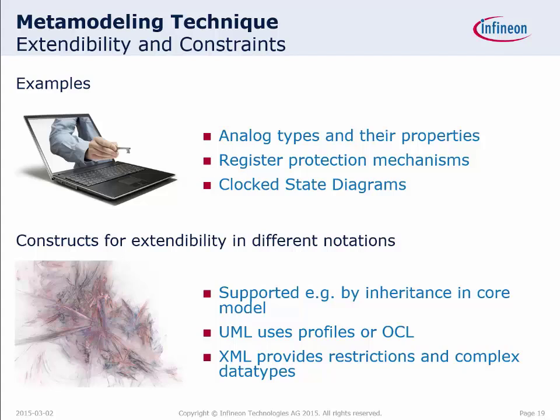If you want to do analog and digital modeling and you have a mixed-signal system, you have to deal with analog types in your digital design environment. Some projects want to still be able, after synthesis, to simulate analog in detail, which means you need some special analog types. Other projects are pure digital and don't care about all of this. So somehow you need to deal with this.